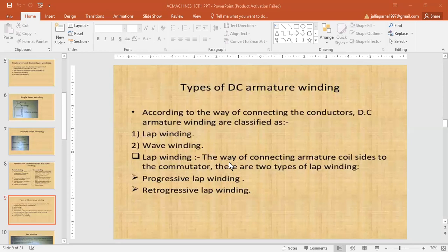otherwise it would be difficult to place the coils properly on the armature. For example, if YB and YF were both even, then all the coil sides and conductors would lie either in the upper half of the slot or in the lower half. Hence, it would become impossible for one side of the coil to lie in the upper half of one slot and the other side of the same coil to lie in the lower half of some other slot.